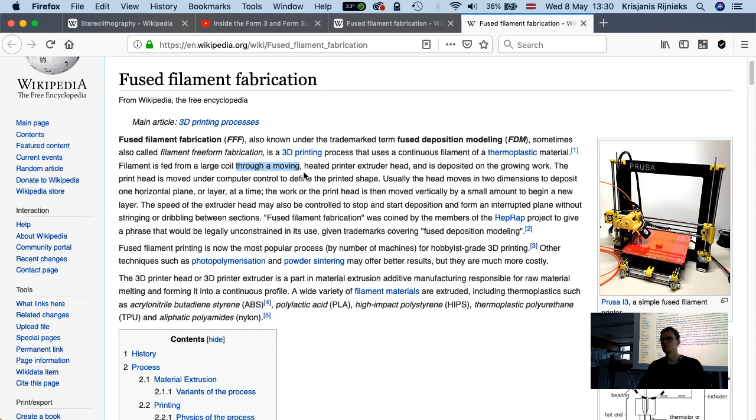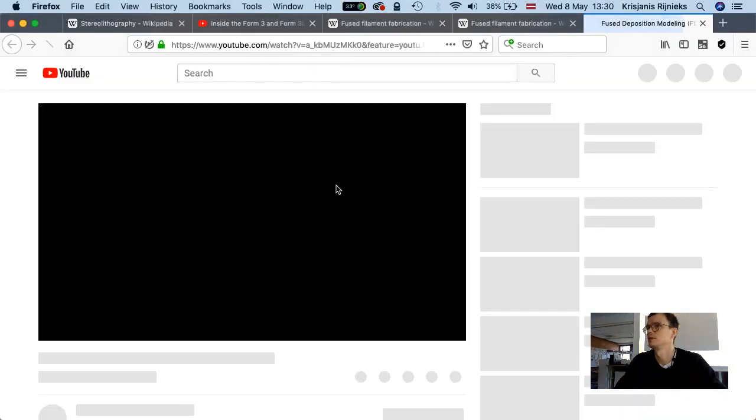It's not necessarily the most precise because you always will have a visible layer height, although with special chemicals you can also post-process and reach a really nice surface finish. But still, it's the fastest. So with FDM, you would do the first 10 prototypes until you see that the functionality is right, and then you maybe would move to other technology, to SLA, or maybe you will start to develop a mold, a tool for injection molding or similar. So let's look at the YouTube video, one of thousands of YouTube videos about this.